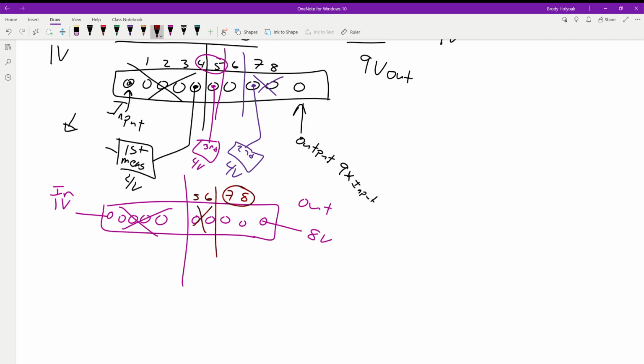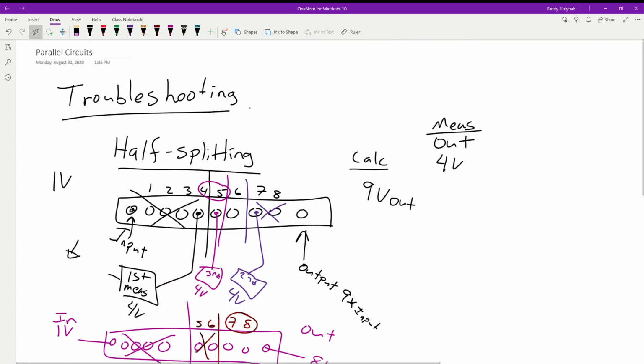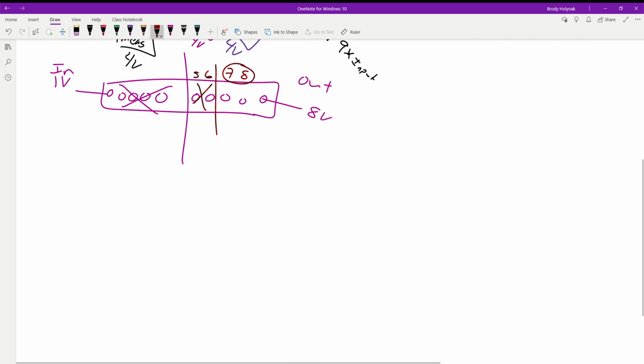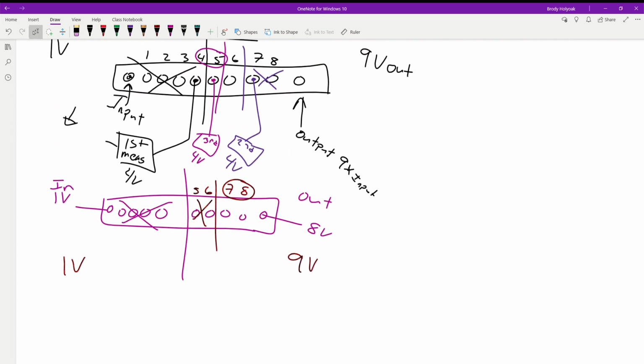So even with this, we can have problems. We go in there and we find out, yep, between 7 and 8, again, I missed my outputs by 1 row on our breadboard. I moved that wire, connected improperly, and now my whole circuit moves away. Now I've got 1 volt and 9 volts. But this way, if you notice, we had to do a series of 3 measurements, and then some deductive reasoning here. And then we took a 4th measurement and found that, yes, that's where the problem was.